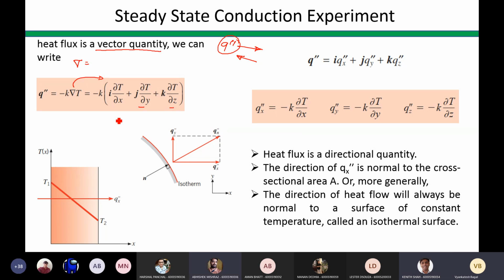Yes, sir. Now look at the diagram at the bottom left corner of this slide. What we see is the temperature plot, right? Temperature distribution. So temperature is a function of x alone. So it is plotted on the y-axis, and on the x-axis we have the length of that rod, right? Length of the rod. So don't think that this is the temperature distribution for a slab.